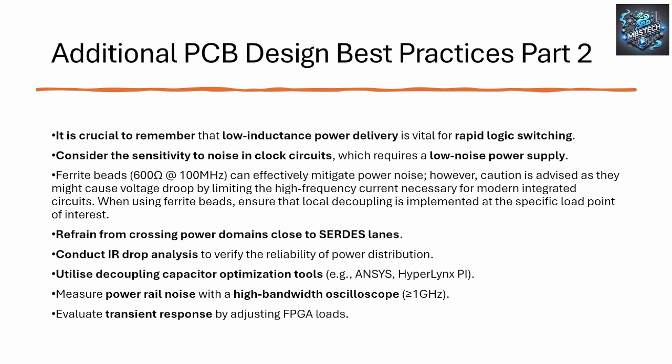Don't forget another thing that people think of. People go, oh well, I've got a 1 gig scope and I've got a 1 gigahertz probe, but you haven't got a 1 gig system, because it's a combination of the 1 gig scope probe and the 1 gig scope. You've got much less than that. So if you're looking for 1 gigahertz frequency signals, you need your 3.5, 4 gig probes and your 10 gig scopes, just so you can really look at those signals. Okay.